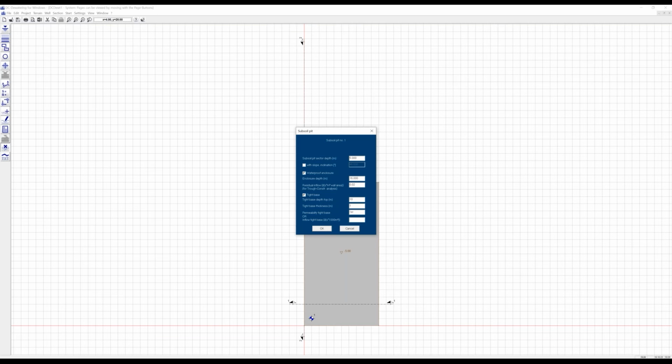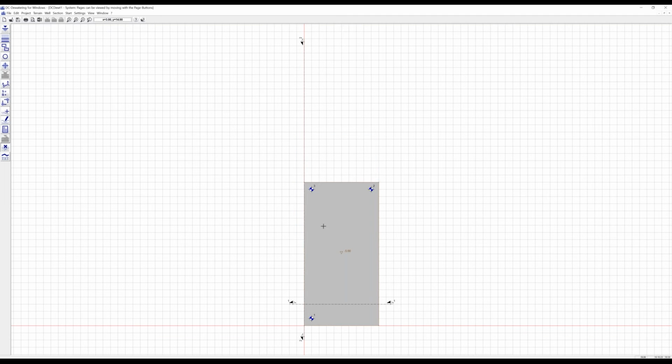E minus 8, for example. As an option, we can define the inflow through the base per 1,000 square meters. Now in this case, we just want to pump the foundation pit empty. That means we have a certain residual inflow and our pumping capacity must be higher to have a certain capacity for pumping this volume empty, all the water which is inside of the foundation pit.